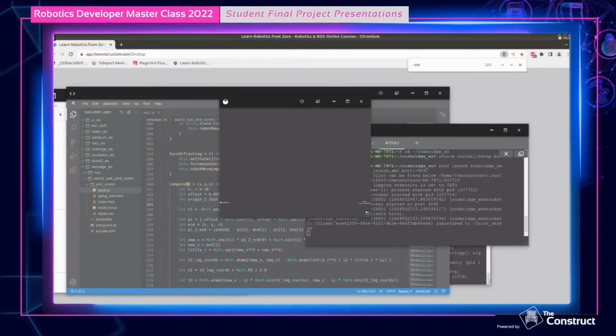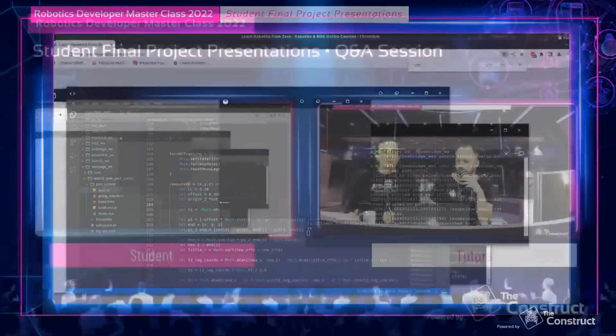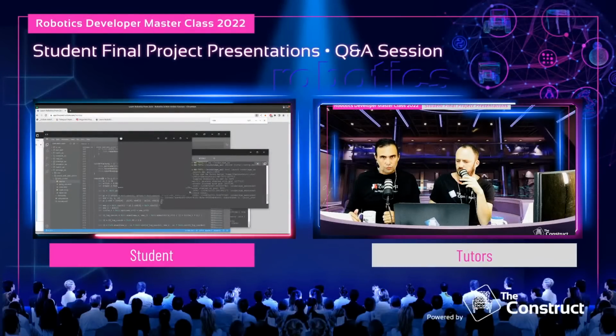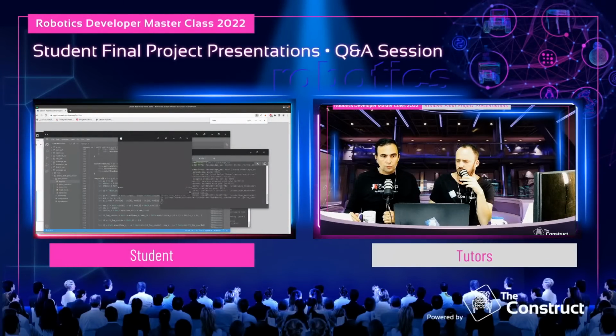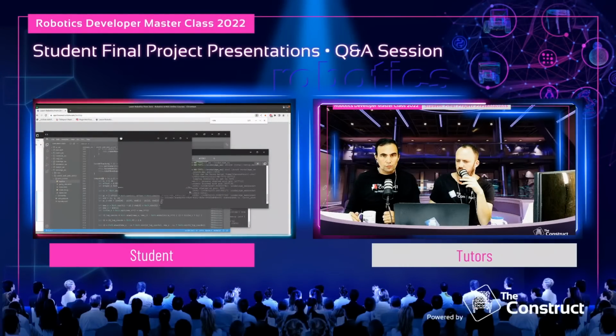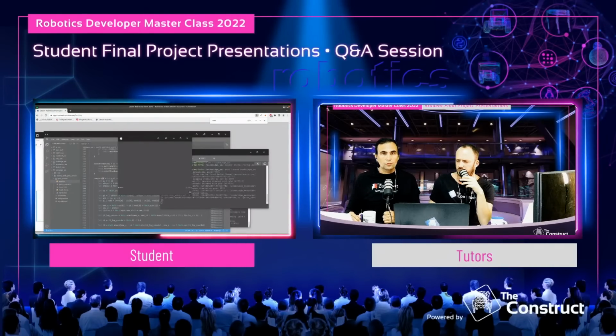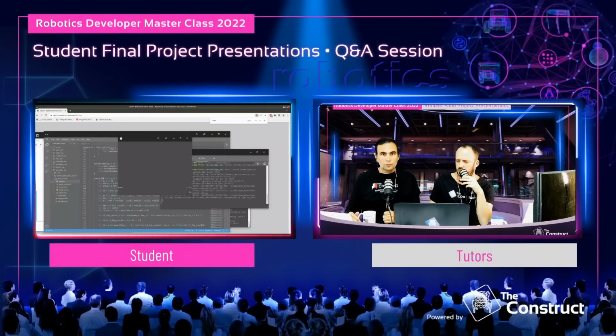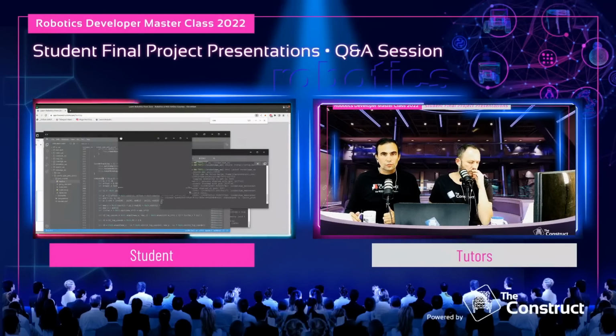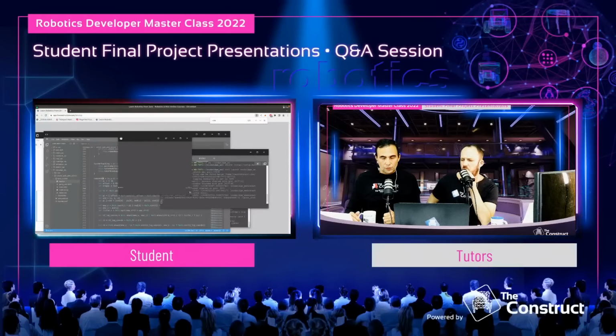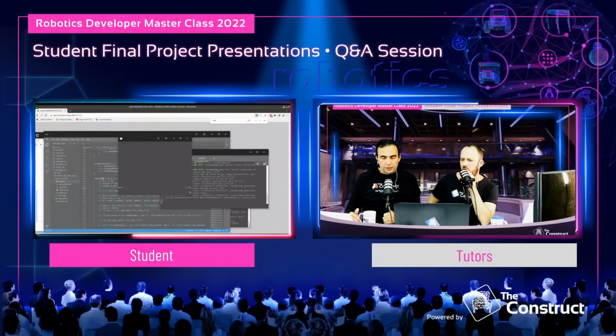For our robot, the controller is running on the hardware, because the hardware can run really fast. I think it's 10 kilohertz. Yeah, 10 kilohertz. And so really what we're doing here is just sending position goals to the hardware, and then the hardware is running the control loop.